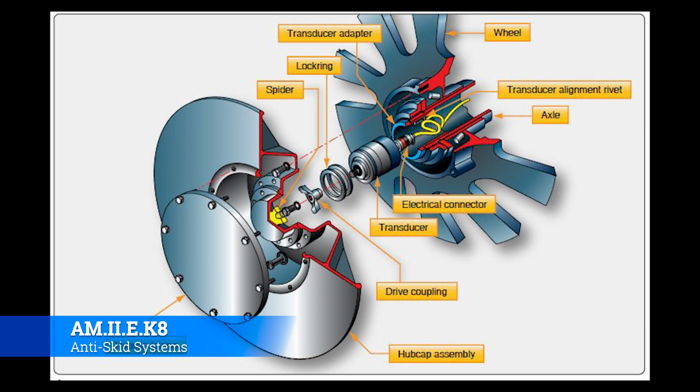So basically, you have a mini electrical generator down there, and as the wheel speeds up, there's a voltage output. It says, hey, we know that at this RPM of the wheel, given these conditions, we produce this amount of voltage at this frequency, and so on and so forth. That allows the airplane to know how fast that tire is turning based on the electrical output. Really cool, ingenious way to employ electronics into the system.